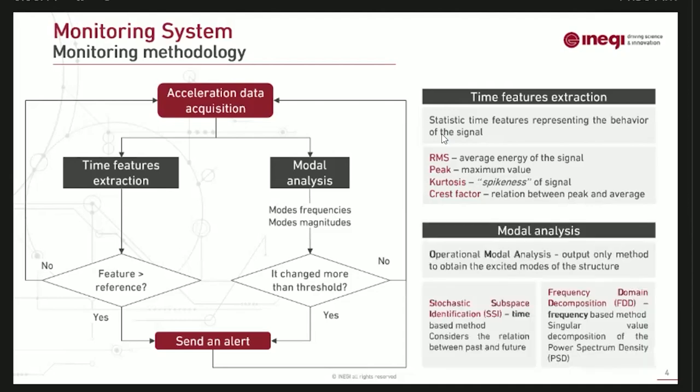Then in the modal analysis, since we do not know what input excitations are acting on the press, we have to use operational modal analysis. With that, we only need the data that we are acquiring to get the modes that are being excited. We tested two methods, one time-based, the stochastic subspace identification, and one in the frequency domain, the frequency domain decomposition.